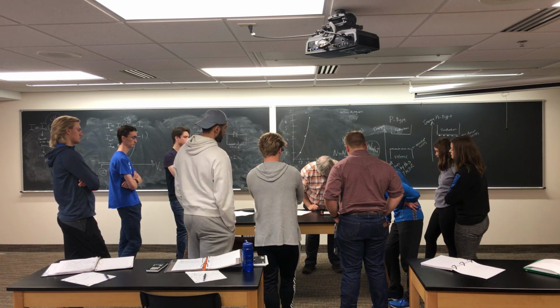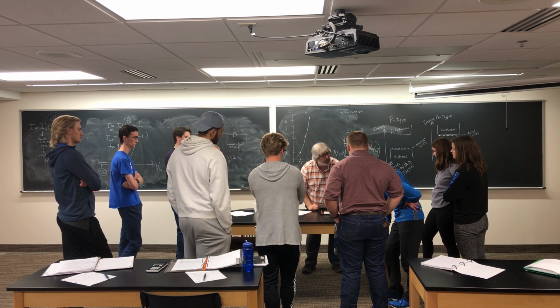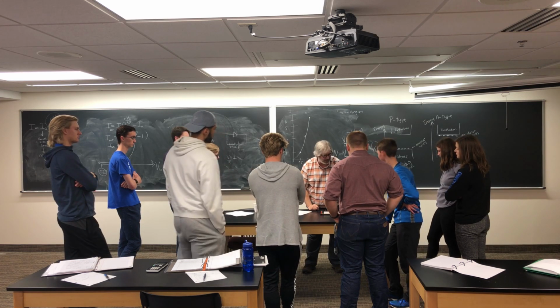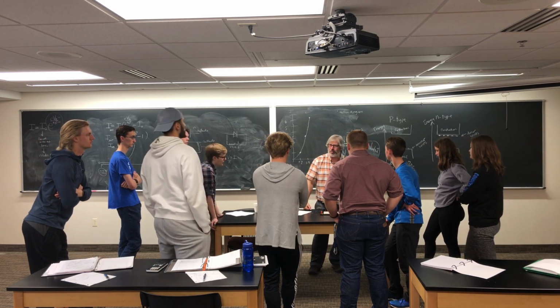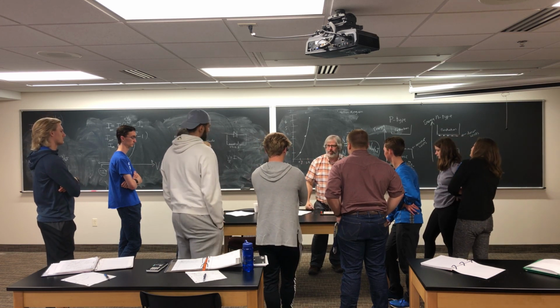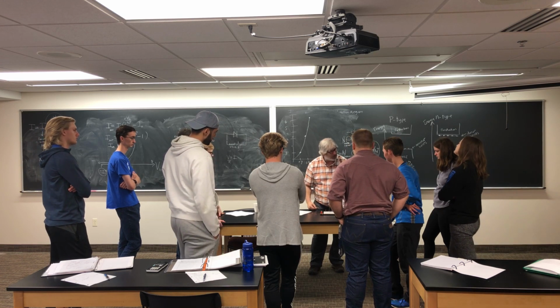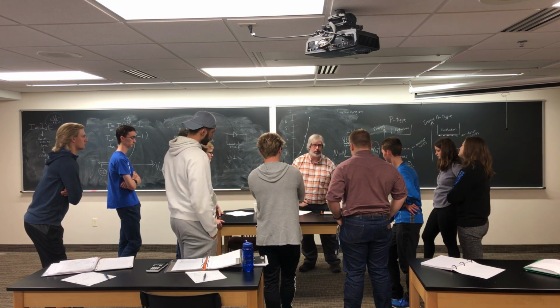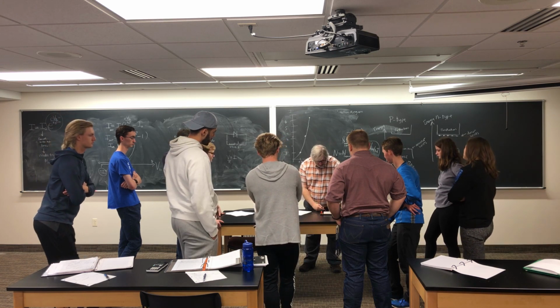You might see the needle goes basically nowhere. So when I reverse bias it, at least I can't see it on this. If I actually got an ammeter that measures in microamps, I might see a little bit. But since this is milliamps, I'm not going to see anything. So I increase that voltage. So nothing going the other way. So it's a good switch in that way.